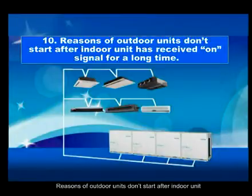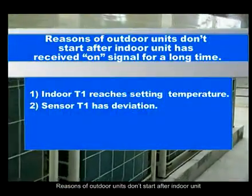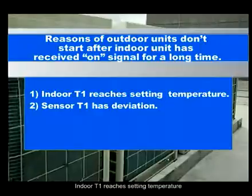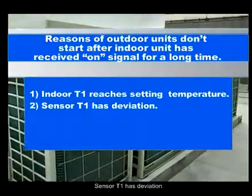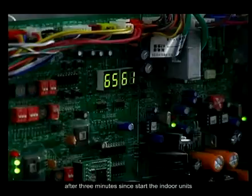Reasons why outdoor units don't start after the indoor unit has received the on signal for a long time. Indoor T1 reaches the setting temperature. Sensor T1 has deviation. Check the capacity requirement of the outdoor unit 3 minutes after starting the indoor units.